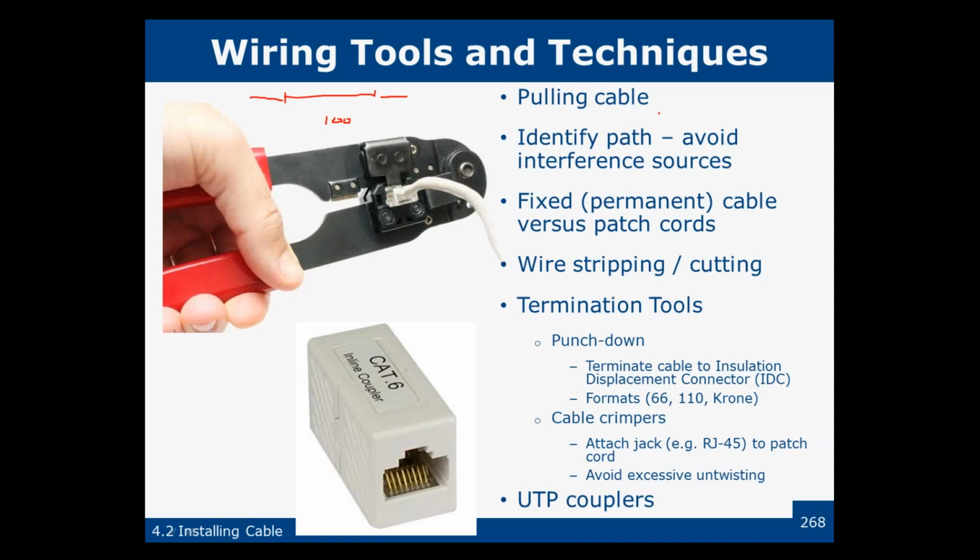When you pull the cable, you should leave a loop, what's called a service loop, at the end, so that you have a little bit of play with it whenever you want to do something with it. When you cut it, you want to cut it square, and usually we're going to use a scissors, and you really do need to get these square, because when you put them into the connectors, if they're not square, you're not going to get